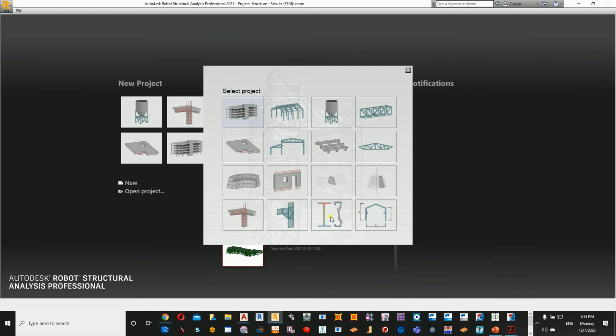Okay. A lot of engineers, what they are doing, they will come to ETABS, they will change only the grade of concrete. Now the software does not only understand the grade of concrete, it understands the E value, which is Young's modulus. If you are not changing it, it means that you are telling me that the cross section is the same all over. Okay. So when it comes to parameters, you need to be careful what to choose and how to choose.